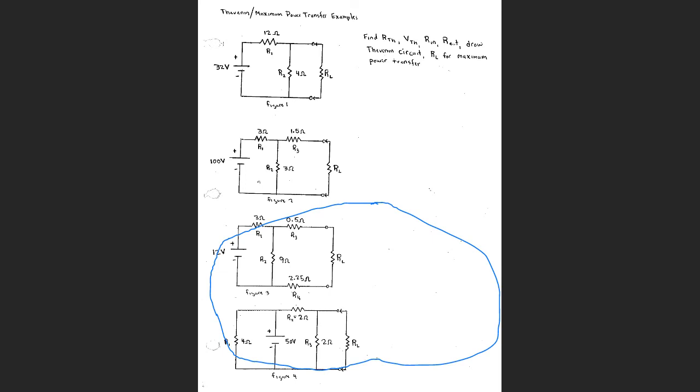So if you think about it, what path is current flowing through in this circuit? Well, current is coming through here, so this is going to have to push through R1. Will it have to push through R3? Well, the answer is no, because it's open over here. When you take the load off, no current can come this way. So the battery has to push through R1 and R2. It just sees these two resistors and they're in series.